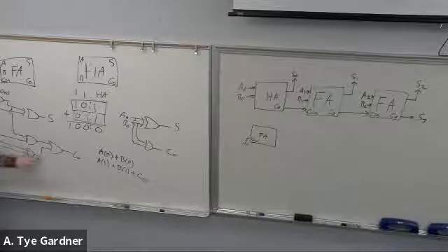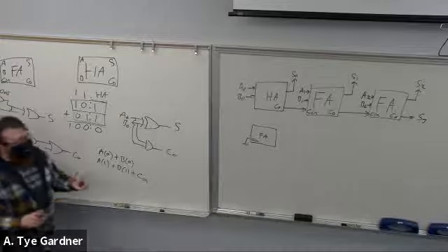So the first carry out doesn't get generated until I've waited 30 nanoseconds. And now if I do that over and over again, this carry out goes to the next carry in, and then I have A, B. So I've got potentially 3 gate delays, maybe as few as 2 if it's just there. So let's call it 3 gate delays for every carry out.